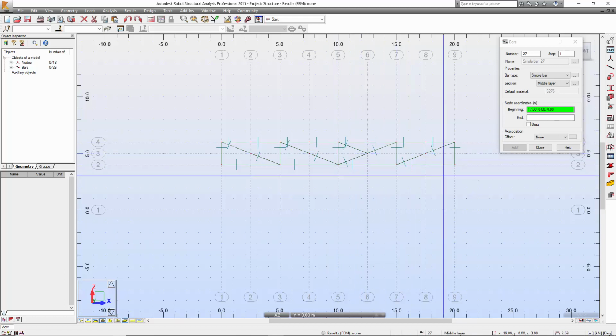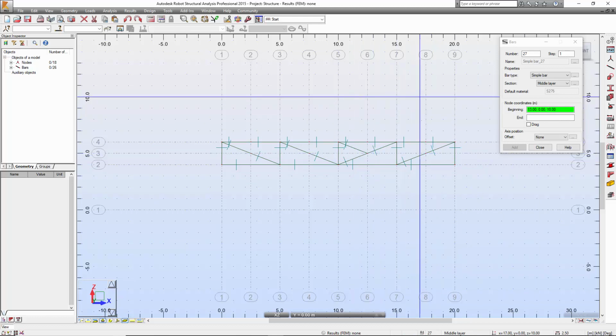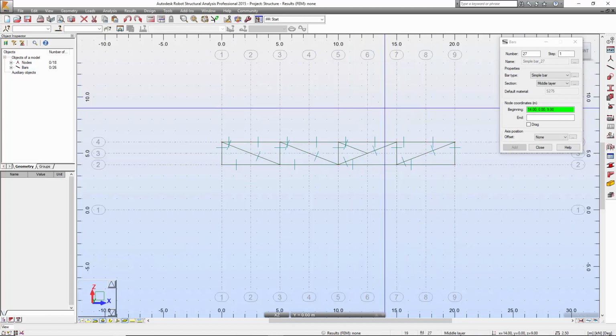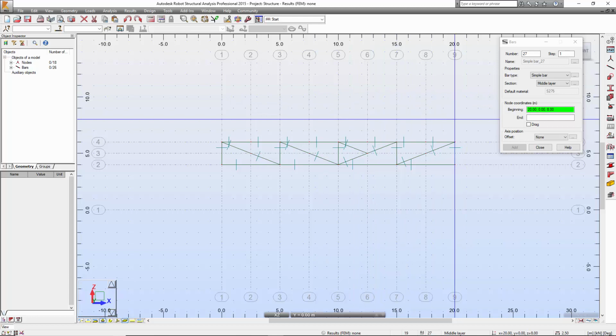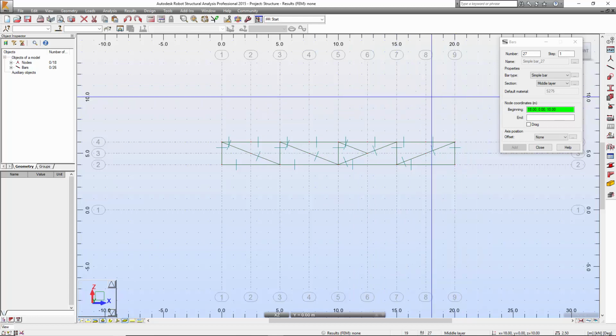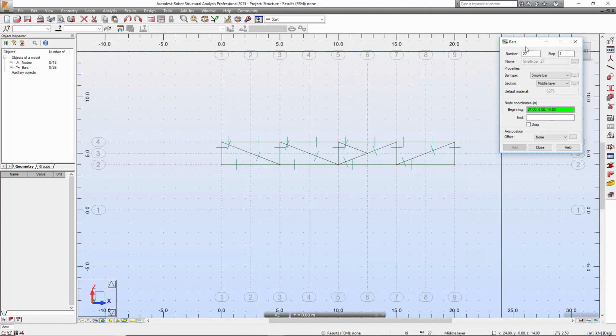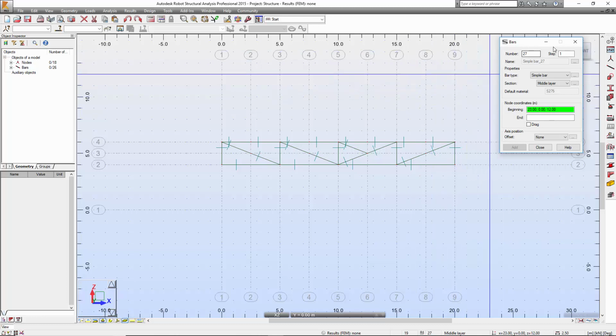To delete it is pretty easy. You need to switch from the join mode to the select mode. The easiest way in this mode is to press the ESC key again, or you simply click on close of this window and then say both are okay. So let's do this one. Press the ESC key first.